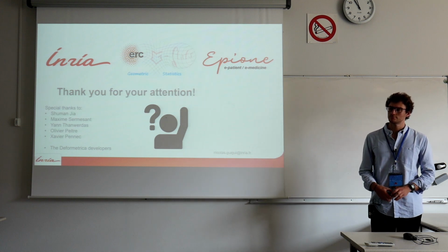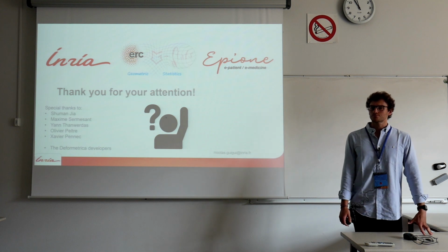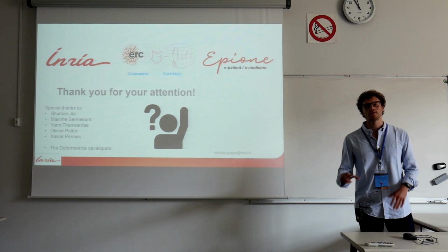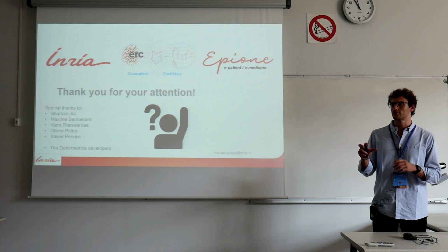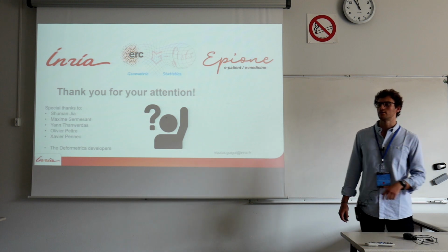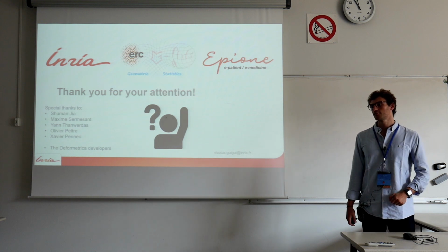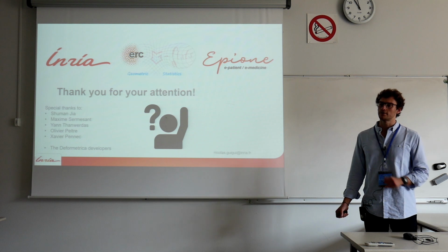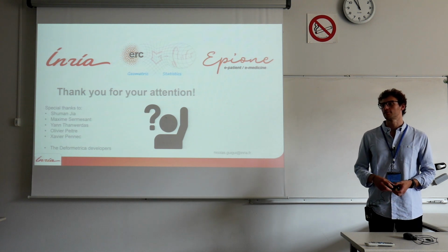In the implementation, you have control points, right? Did you look at what is the effect if you start having more or fewer control points in the parameterization of the deformation? I tried indirectly. The number of control points is fixed by the size of the kernel. They're spaced by the sigma of the kernel initially, so by varying the size of the kernel, you put more control points at the beginning, and you obtain more precise results. But in practice, here I only used 60 control points for about 1,000 landmarks on the mesh, and this performs very good registration, so we don't need that complexity.